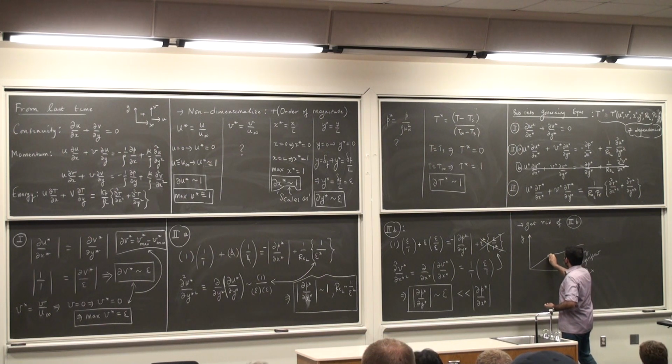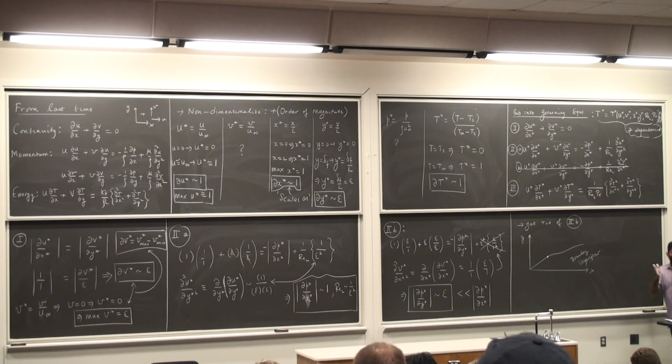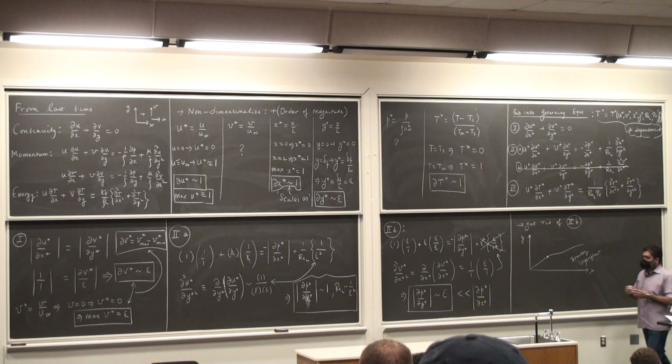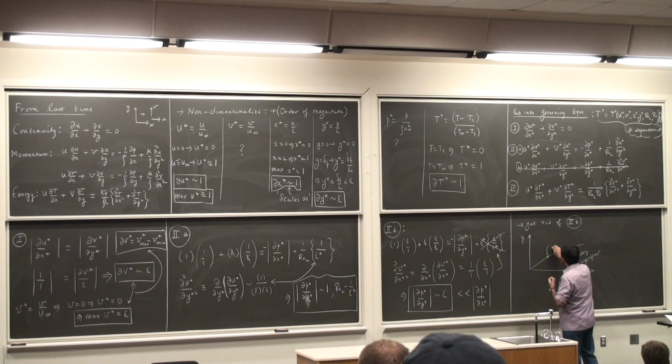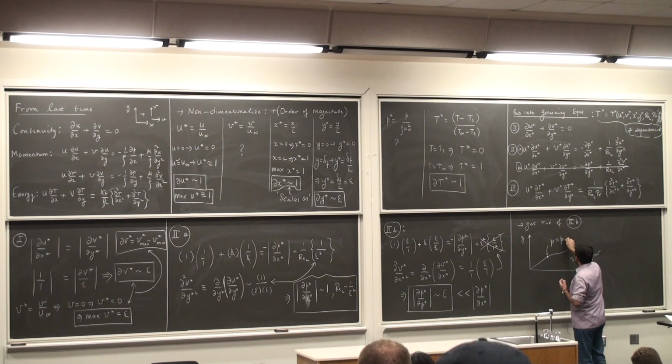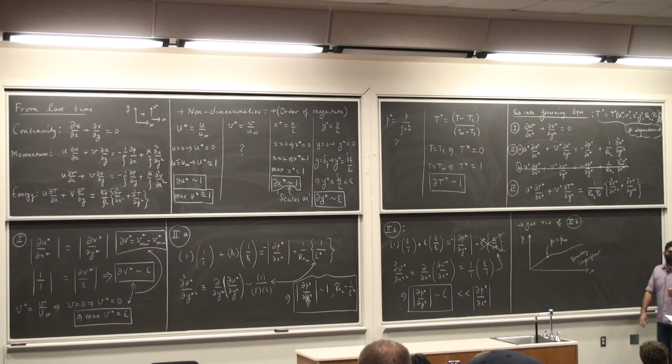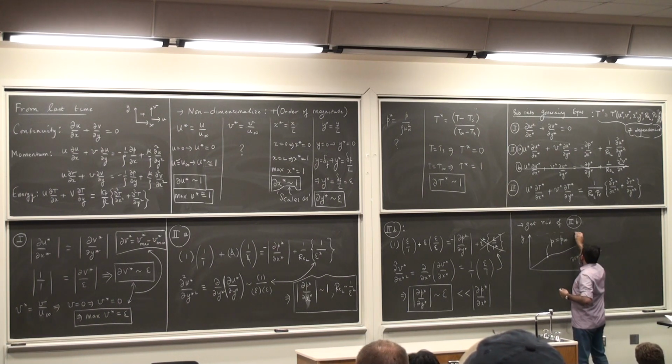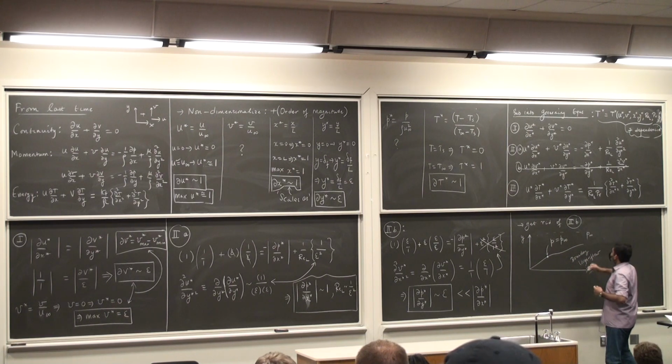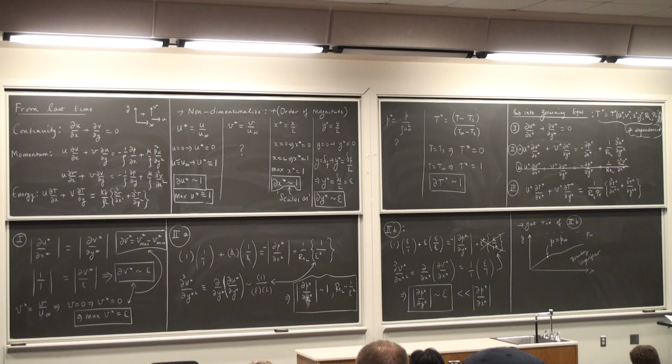So, if I'm sitting at the edge of the boundary layer, the pressure is P infinity. Does this make sense to everybody? Everywhere else the pressure is the same. So the fluid is flowing past, and so the pressure here is P infinity, and so on and so forth. Within the boundary layer, the things are taking place, we don't know what they're doing.